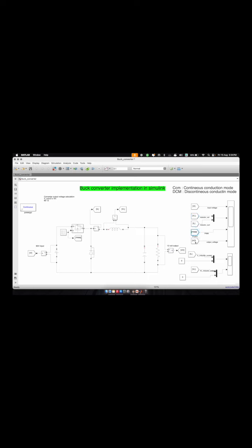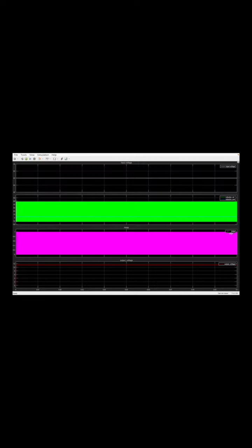And we have this PWM, showing how the switching is happening, and we have this output voltage waveform. So let's see how these things look like. We can see here the input voltage is 60 volt, and along with that we can see the inductor voltage and the current over here. Inductor voltage is around 50 volt, and you are getting a PWM signal here.